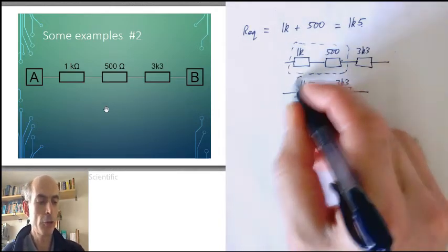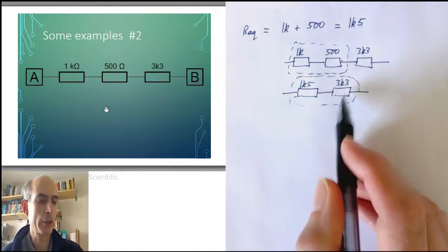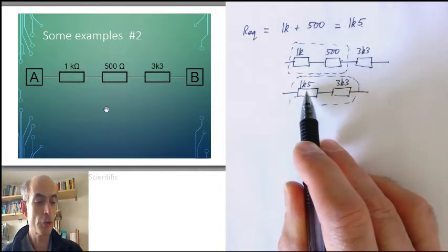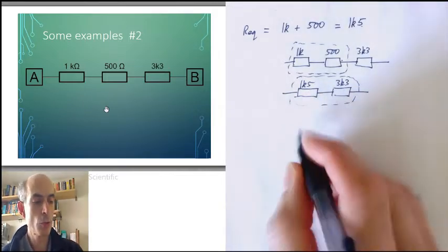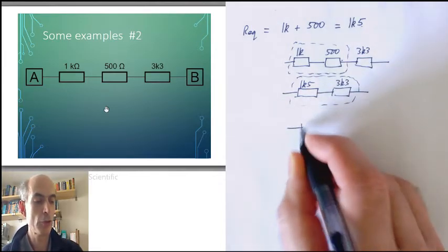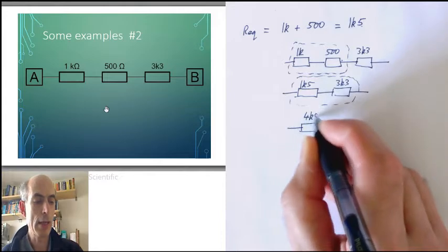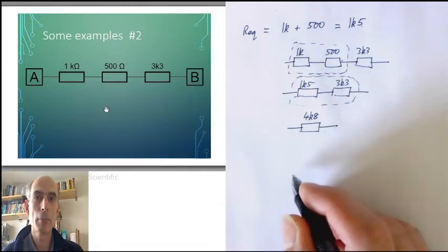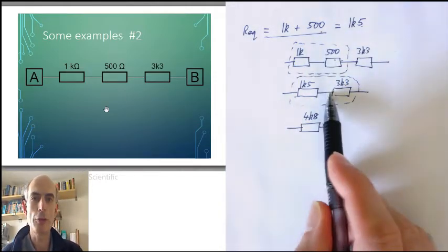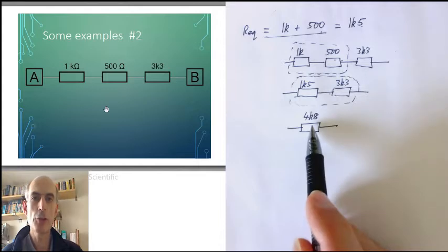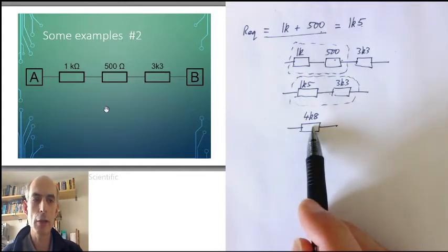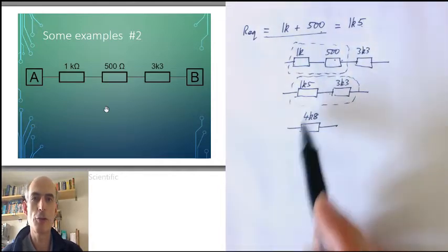And now we could consider this as our resistor network. We've got two resistors in series. The equivalent resistance of these two resistors in series would just be the sum of these two resistors, which in this case would be a single resistor of value 4k8. So, we've applied this first formula, adding up two resistors, twice. And we've got a single resistor here at the output, rather than applying that formula for three resistors in series.